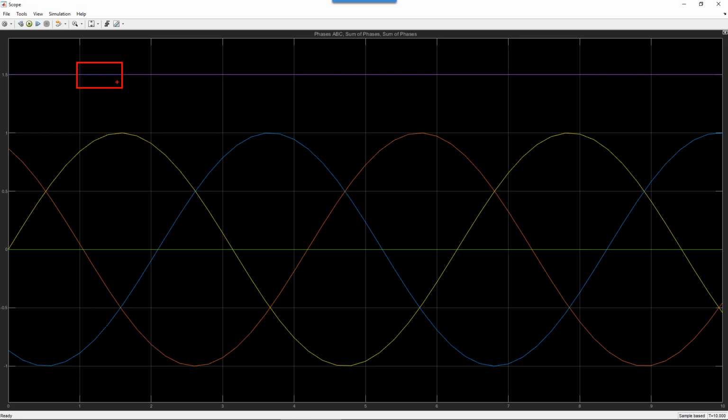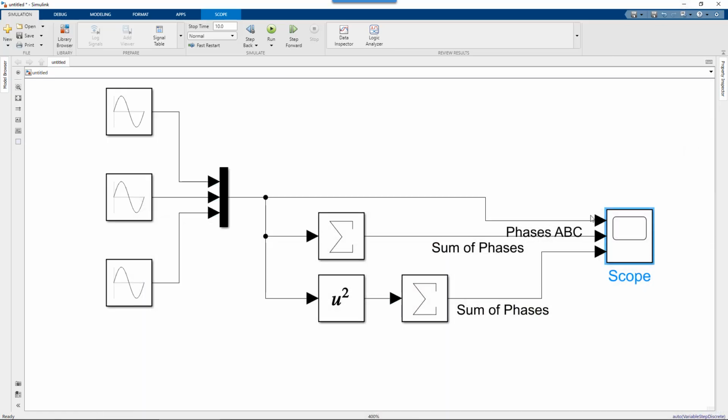But with a three-phase motor or a three-phase generator, you can essentially have constant power on the electrical side, which means you have constant power on the mechanical side, which means things like torque ripple and other such dynamic effects are greatly minimized when you compare it to a single phase or a two-phase system.